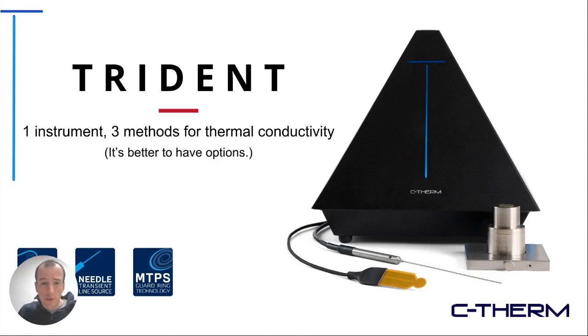The needle probe, it's really all about robustness. This is a really strong sensor format. It's sheathed in stainless steel. It is primarily used for very sticky situations. So if you think of a polymer melt or some of those situations where the sample may bond to the surface as you're testing it, the needle probe or transient line source, TLS, provides excellent robustness.